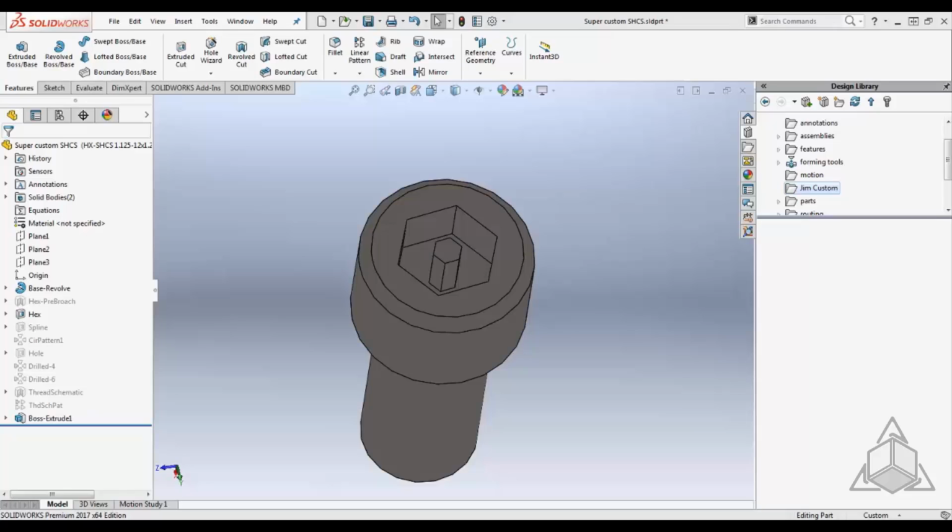I'm Jim Holtz and today I will be covering my tips, which include mate references, hiding components, and selecting through transparency. For components that you typically mate the same way every time, you can set up mate references to define the mates used and the component geometry being mated.